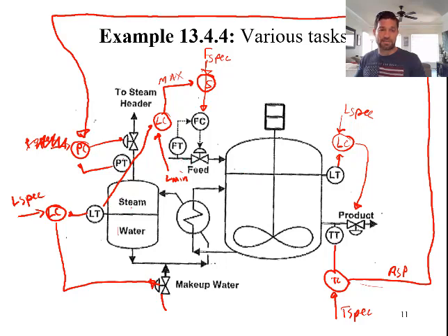In order to bring this level down, the objective of the process constraint loop is to get it to the process constraint. If I want to bring this level down, I want the maximum amount of heating I can have, because I'm producing more steam than the makeup water I can have coming in, which means I need a max flow coming to the system. Therefore, this would be a low select controller.